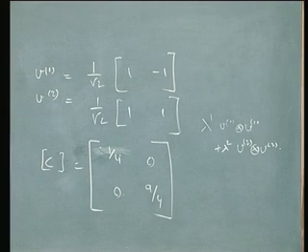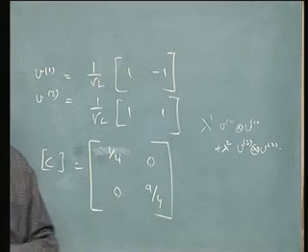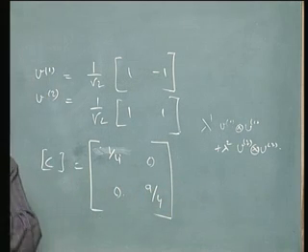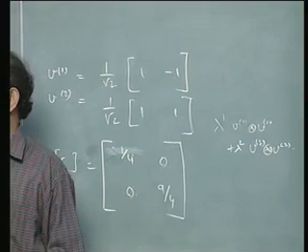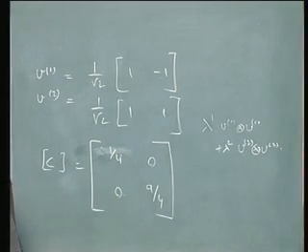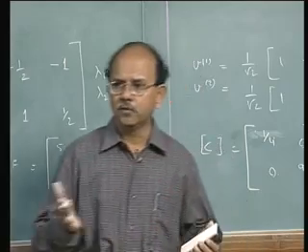This is exactly what you do, for example, when you do vibration problems. You find out the eigenvalues and eigenvectors, and then change over the basis. Your original basis is now replaced by the eigenvectors. What exactly you do? You decouple the governing differential equations.